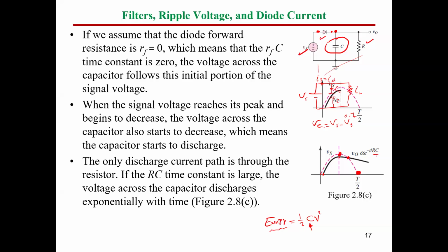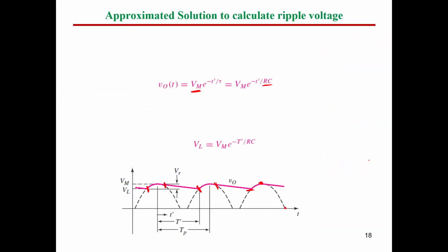This is required here because the voltage is not going to decrease quickly, so it will take a longer time. This means the voltage will not drop to 0 and will continue with higher values, or technically, we say with less ripples. What is the meaning of ripples? We will see this together in the coming slide.